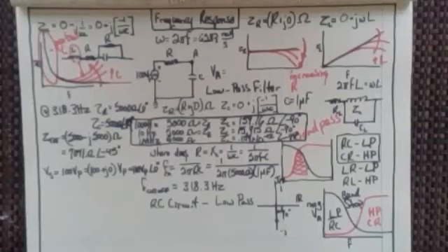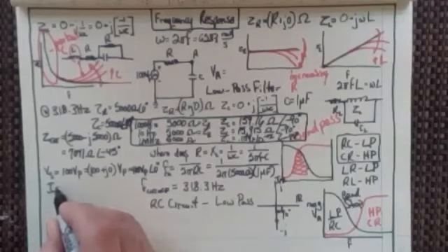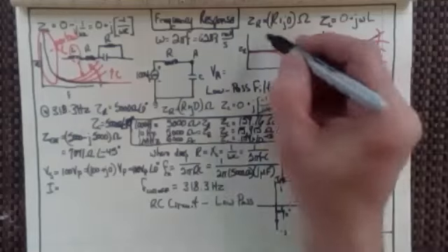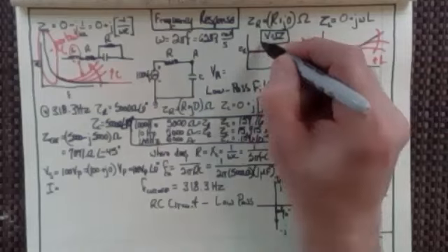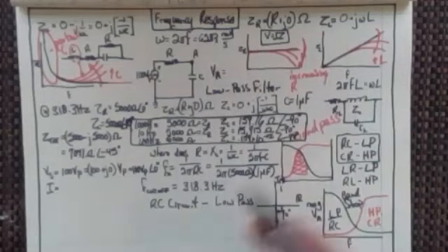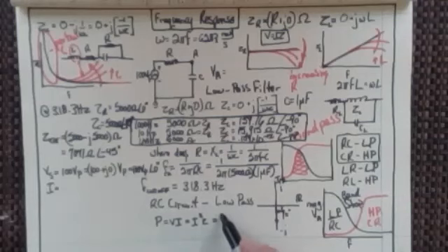So now we know exactly what's going on there, and we could actually find out what the current is. What is my peak current? Because I know Ohm's law. I love to write Ohm's law, by the way. V equals IZ. And let's put a box around it. Don't ever forget that. Oh, and you also want me to write the power equations? Yes, that's right. Power equals VI, or it equals I squared Z, or it equals V squared over Z. And remember, all of these are RMS for power, all RMS for power. So let's get back here.